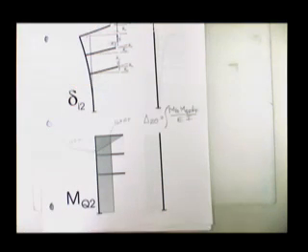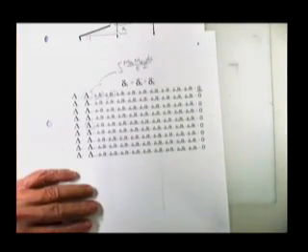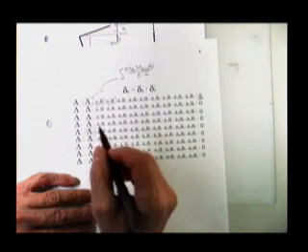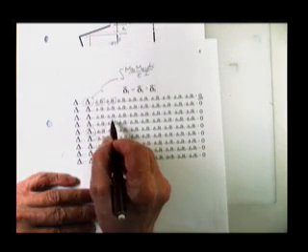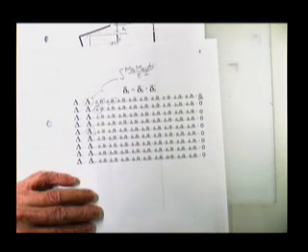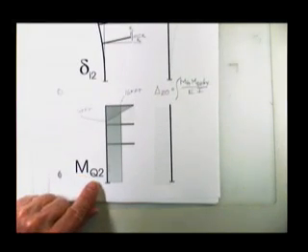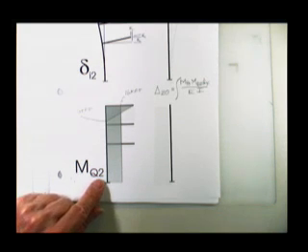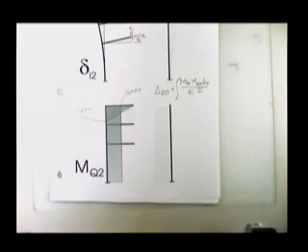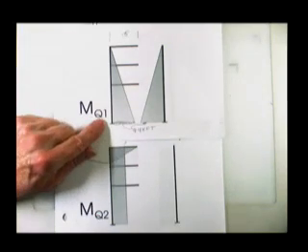If you are home, your television is broken, your dog has died, so you're looking at these equations. It's the only thing I can imagine that you would be looking at these equations, and you want this guy right here, delta 2, 1, you would go looking for the unit load applied in the number 2 direction, and you would combine it with the moment diagram M sub Q1.